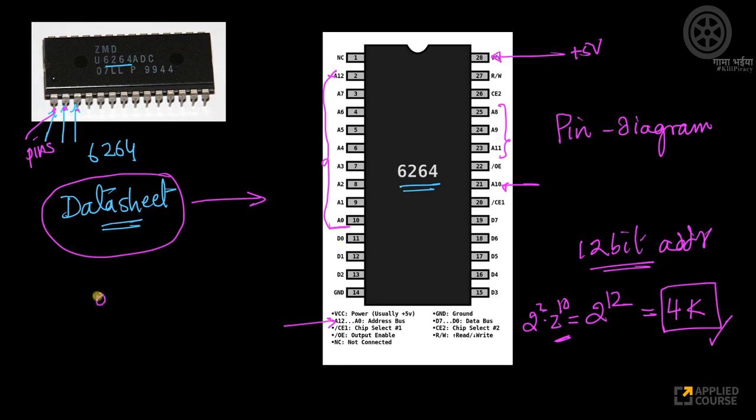Now, physically, you have these 12 bits. Look at this, you have 1, 2, 3, 4, 1, 2, 3, 4, 1, 2, 3, 4. The 0th bit has to be connected here. The first bit has to be connected here. Second bit here. So from the CPU, when you do the actual connection, you have to physically connect the 0th bit here, first bit here, second bit here, and so on and so forth.